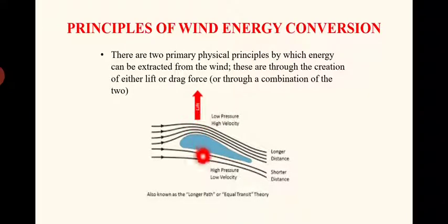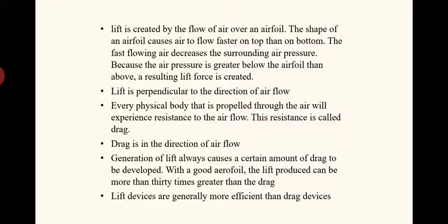So that difference in pressure will act as a force. That force is known as lift force, and it is always perpendicular to the flow direction of the air. Okay, so lift force is always perpendicular to the flow direction of the air. So with that lift force, the blade will be rotating continuously. Okay, that is the basic principle of lift force.